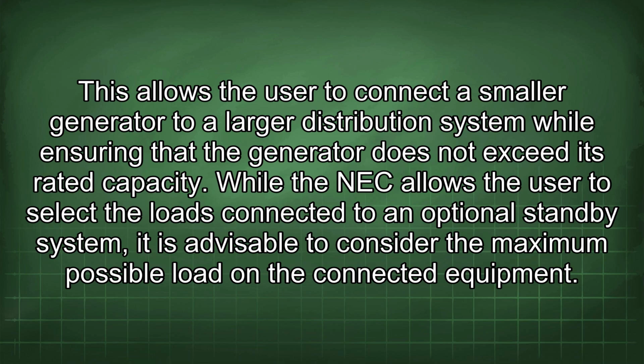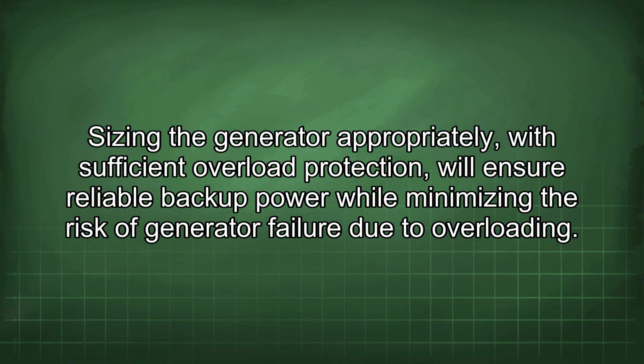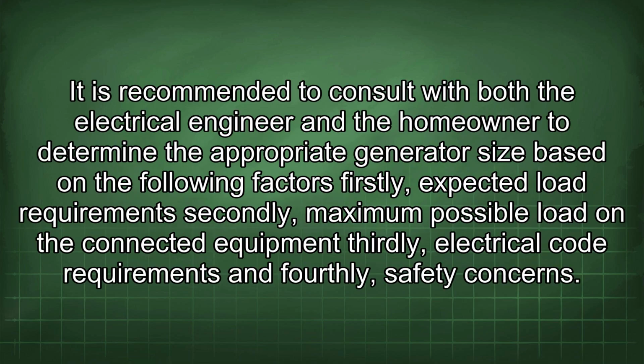While the NEC allows the user to select the loads connected to an optional standby system, it is advisable to consider the maximum possible load in the connected equipment. Sizing the generator appropriately, with sufficient overload protection, will ensure reliable backup power while minimizing the risk of generator failure due to overloading. It is recommended to consult with both the electrical engineer and the homeowner to determine the appropriate generator size based on the following factors.